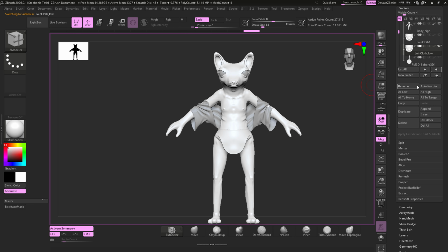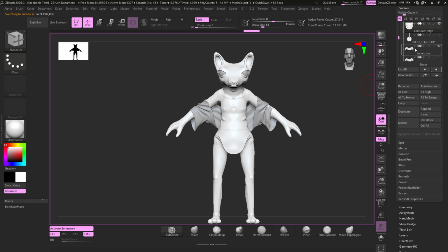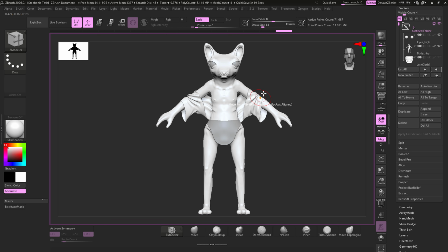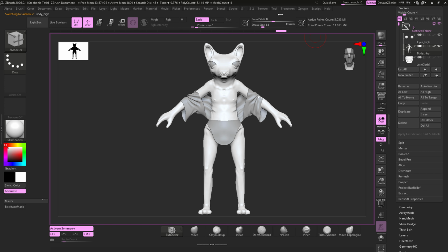And this time I'm going to think about what materials I'm going to have on my mesh, because ideally we're going to export our high poly versions as a FBX according to the material set that we assign. So if you're not using UDIMs and you're assigning separate materials, I would export probably just my body in one.